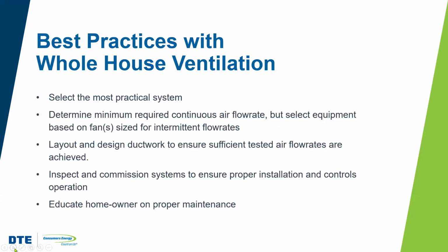Some of the best practices with house ventilation. Obviously, you want to select the most practical system for the particular application. So it's not always that you need to go to the full-blown system with the energy recovery. It may be that this is a smaller home, and it very well may be that supply air ventilation is sufficient, or even exhaust air, right?